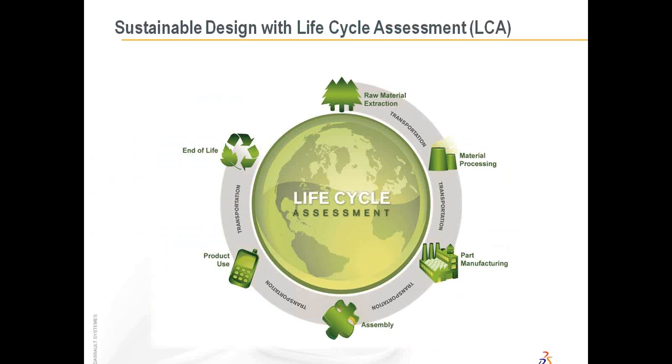So SolidWorks Sustainability uses life cycle assessment, the LCA methodology, to estimate the environmental impacts of your designs or products. So when I say LCA, it covers the entire life cycle of the product, starting from raw material extraction to material processing, manufacturing, assembly, of course the product use part, and then the end of life, which can be either disposal or recycling. And also SolidWorks Sustainability will take care of the transportation phases which occur in between these stages.